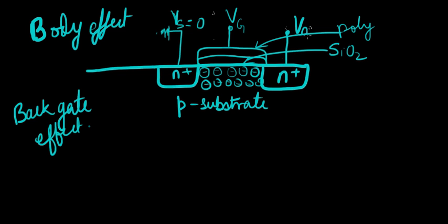You're going to give them positive voltage, and it's connected to the N region, so it's reverse biased. So what we have to look at is the fourth terminal. We have three terminals: source, gate, and drain. What about the fourth one? We do have a fourth one called the body, or the bulk, which is called a P substrate.